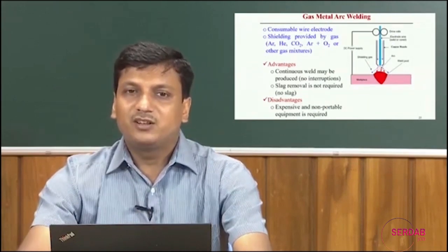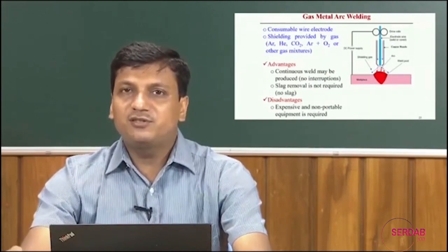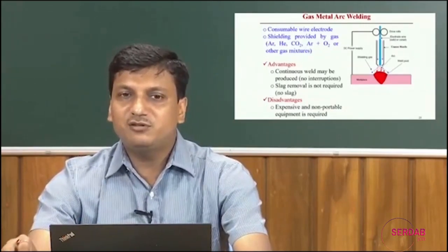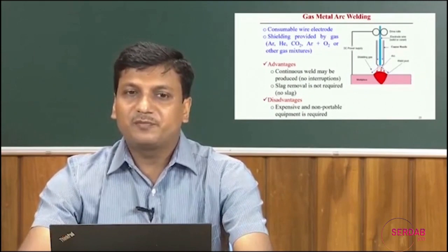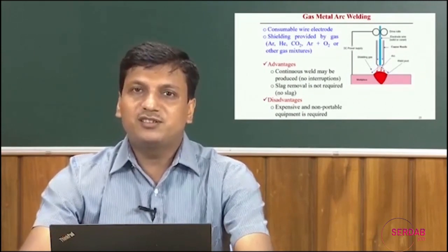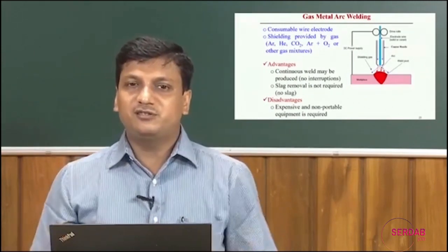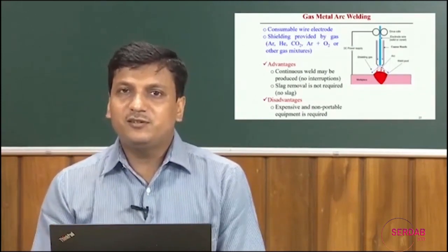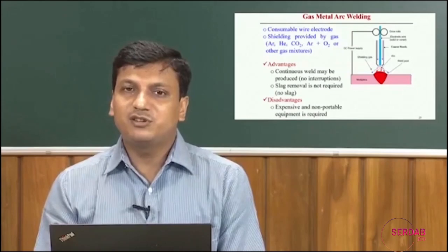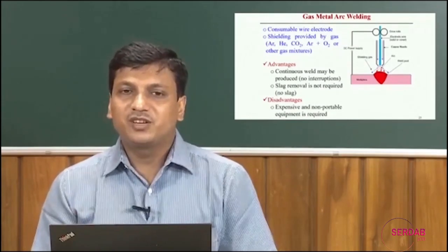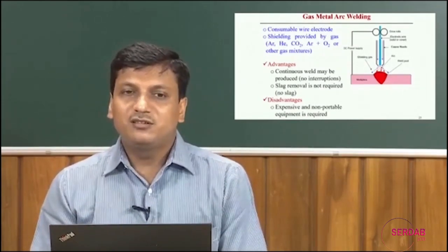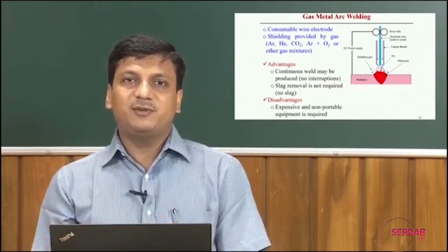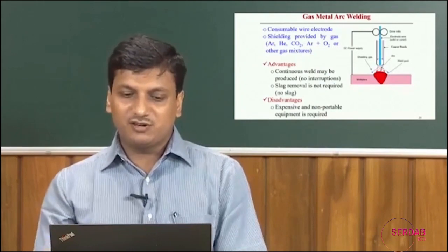and in that sense it is advantageous as compared to the shielded metal arc welding process. But if we look into the disadvantages in general, it is definitely more expensive as compared to the shielded metal arc welding process, because it is also necessary to drive the electrode material according to the consumption rate, or that should be adjusted to the consumption rate during the welding process. So, in that way the equipment is a little bit more expensive as compared to the shielded metal arc welding process.